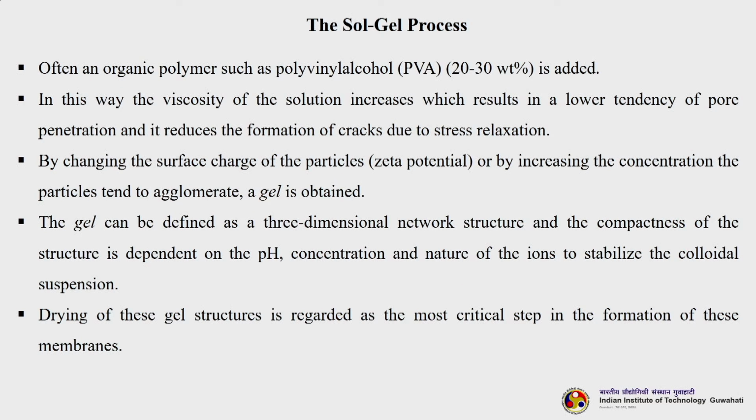Often in organic polymers such as polyvinyl alcohol, usually 20 to 30% is added. Now, in this way the viscosity of the solution increases, which results in a lower tendency of pore penetration, and it further reduces the formation of cracks also due to stress relaxation.